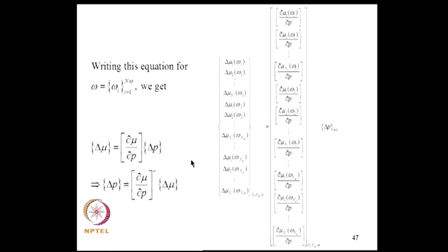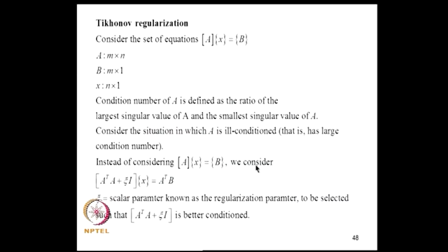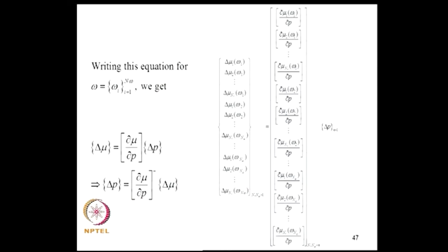We will see that this helps us to deal with repeated natural frequencies. When I considered the derivation of eigen sensitivities, the question of the possibility of eigenvalues repeating was not addressed. If you have a system with certain symmetries, eigenvalues could repeat. In that case, how do you do updating, because gradients of natural frequencies which repeat involve certain additional considerations. Now, what we have done is the generic form of the equation, no matter which response descriptor you use: delta p is equal to some S plus delta gamma.